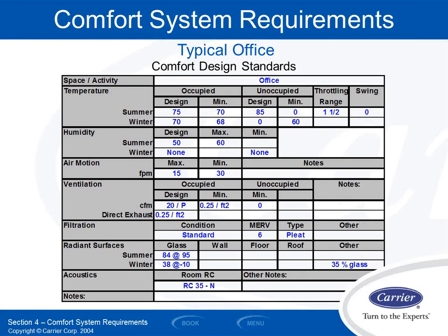Now, I say that's the old school way because sometimes what's been happening with newer equipment, especially residentially, equipment controls have gotten much smarter, and they realize that you've got lots of stages in some of these units, 5 stages, 60 stages, whatever it is, modulating gas valves, stuff like that. And they take into account the fact that most pieces of mechanical equipment are the least efficient when they're operating at full load operation. They do much better at part load.